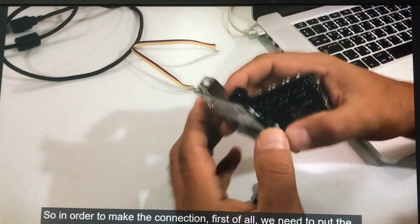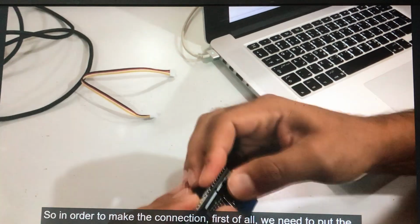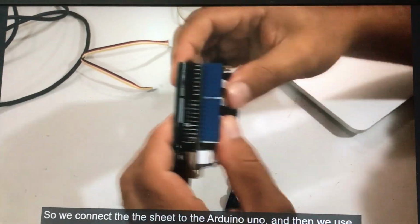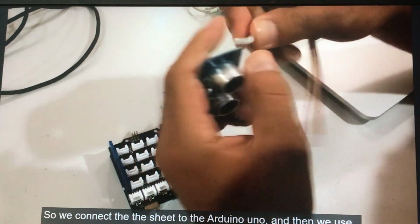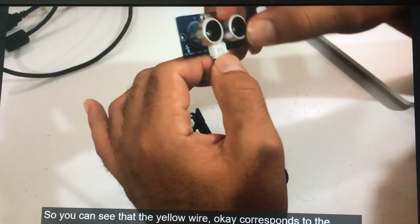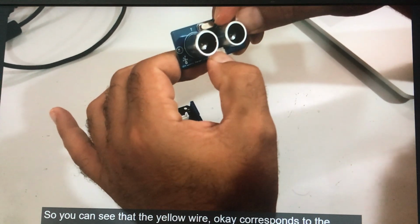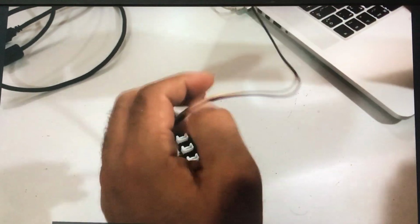Okay, so in order to make the connection, first of all, we need to put the shield on the Arduino Uno, like this. So we connect the shield to the Arduino Uno. And then we use the 4-pin connector, and we plug it here into the sensor. So you can see that the yellow wire corresponds to the signal, the red wire corresponds to the VCC, and the black wire corresponds to the ground pin.